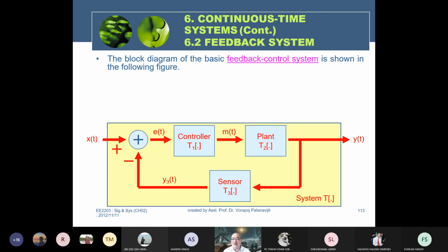If the room temperature is only reduced to 27, it is still higher than 25. There is still some error. Therefore, the controller will still send the signal to the compressor to keep working, until the room temperature is reduced to 25 Celsius. If it is 25 Celsius, it is already matched, the thing that you set is 25, and there is no error.